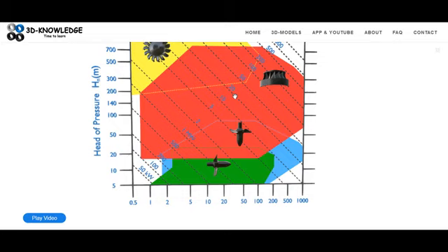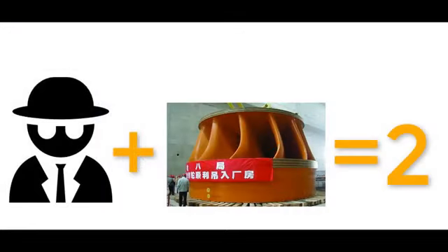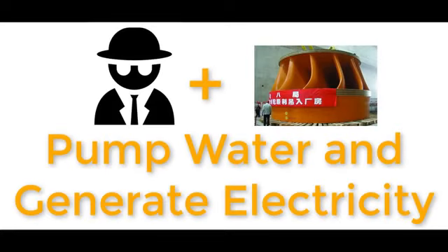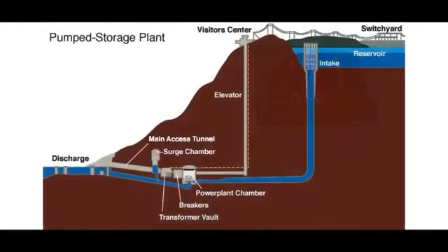The Francis turbine is also what I dub the secret turbine. The secret turbine has two functions, or it can have two functions. If you have a radial flow Francis turbine, you can also use it to pump water. So it has two functions by design. That means if you're taking water from an upper reservoir to a lower reservoir and it's passing through the Francis turbine, you can generate electricity.